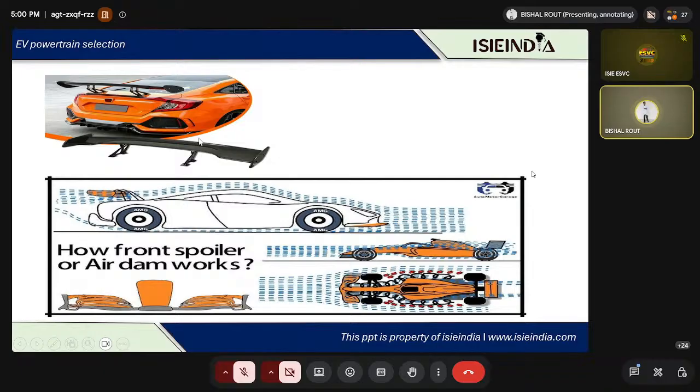Whenever there is a lightweight vehicle and you try to run that vehicle at very high speed, from the bottom you get a higher force, so what will happen is it will lift your rear wheels, basically. That is the reason we create the spoilers over here. So spoilers will take all that air, and instead of directly separating, they create a force above the spoiler, and once they create a force above the spoiler, it creates grip with the tires, basically. The splitter's work is to not allow any accumulation of air in the front of the vehicle.